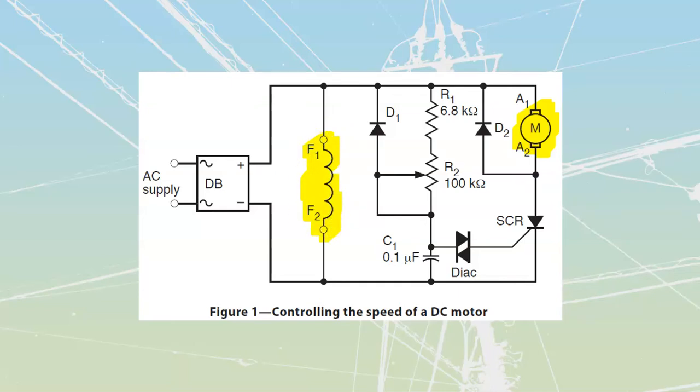It's going to be a field, and by a field we just mean a coil of wire that is going to be placed inside of there that's going to be powered up and it's going to create a magnetic field. And since this has created a magnetic field, we'll stick some magnetic lines of force around there, they're going to interact with the armature, and then that's what's ultimately going to give us rotation. That theory will be covered later on. For now, you just need to know that it exists. First of all, we do need to have constant power to this field. If we don't have constant power to this field, we're not going to be able to establish that initial rotation.